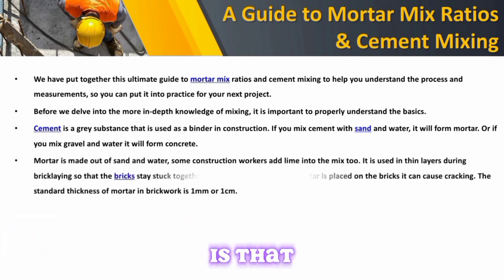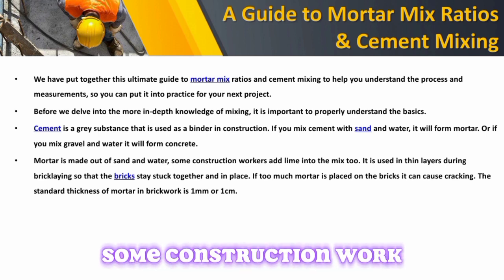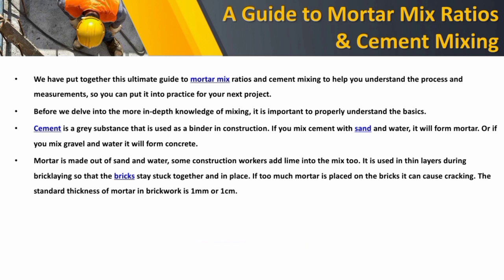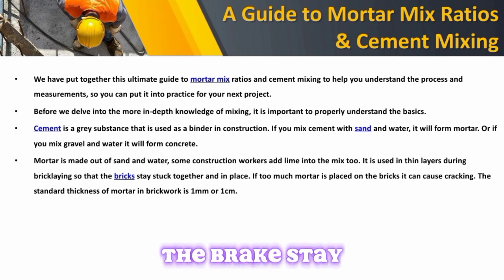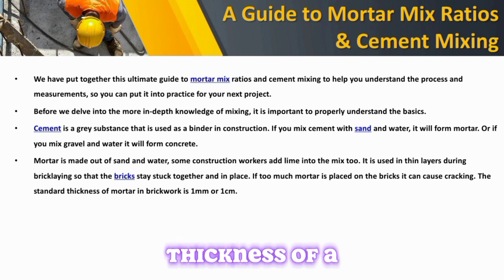The next point is that mortar is made out of sand and water. Some construction work uses lime in the mix too. It is layered during brick laying so that the bricks stay stuck together in place. If too much mortar is placed on the brick, it will crack. The standard thickness of mortar in brickwork is 1 centimeter.